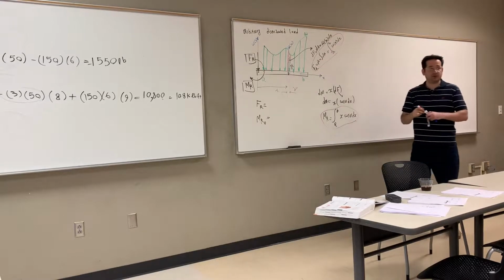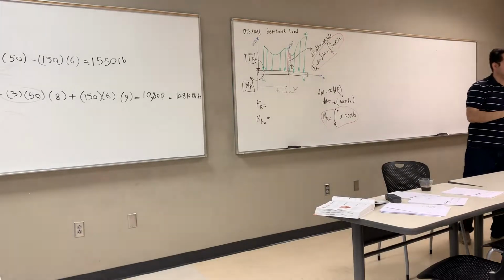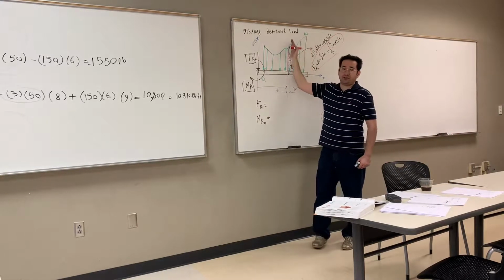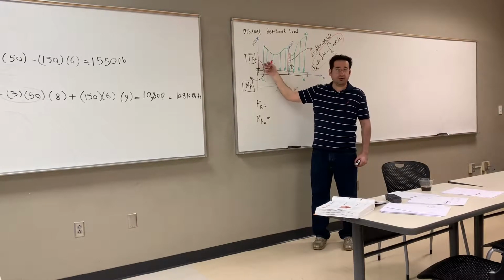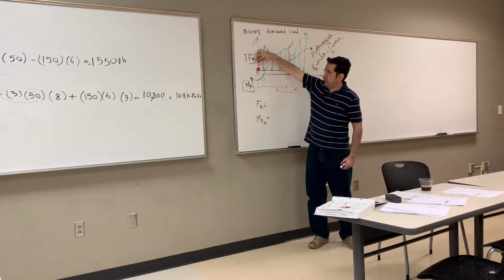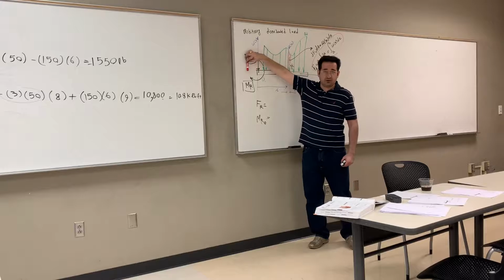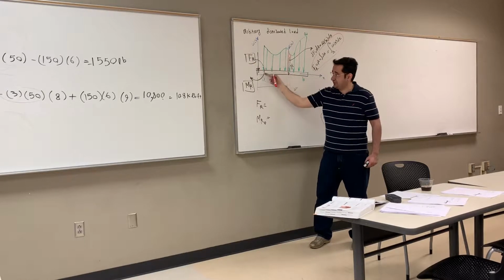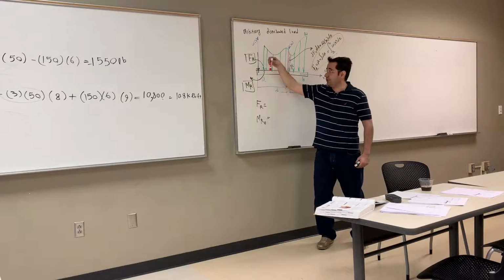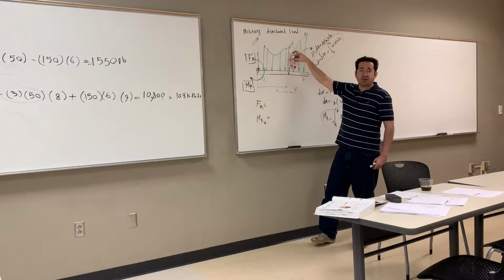I found it, right? Using basic math. Now I no longer have a distributed load. I have these two, one force, one moment. Now I want to move this sideways such that I generate the effect of the moment, so I can go further and drop the moment and only have one force at a particular distance.